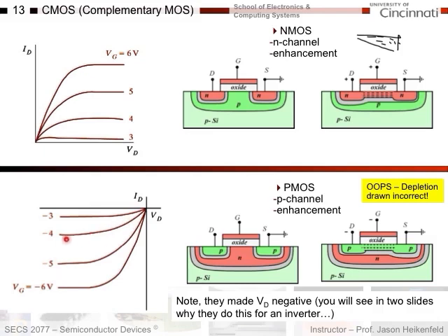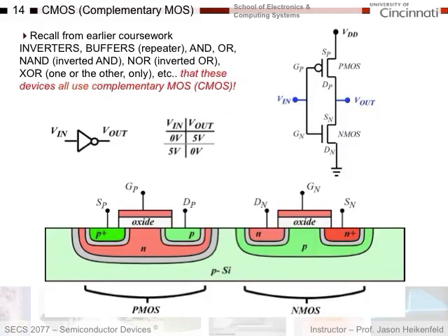I want to note there is one mistake here. I noticed that if I look at my depletion region here, if this is negative here, negative voltage on a PN junction on the P side is reverse bias, right? Well, my depletion region should be thicker here and thinner here, so I just drew the thicknesses of my depletion region opposite here. We'll talk more about that in a second, though.